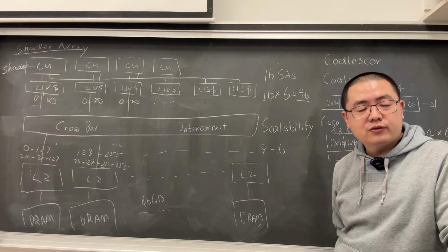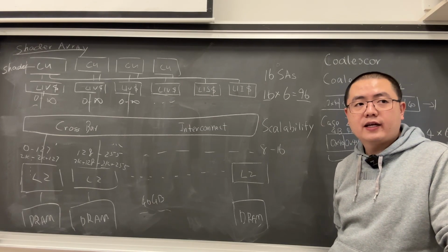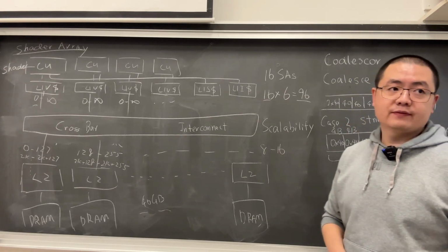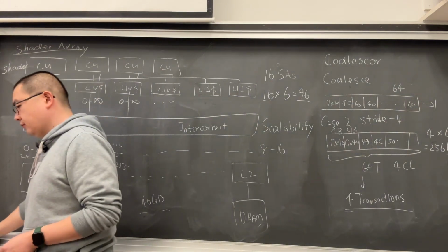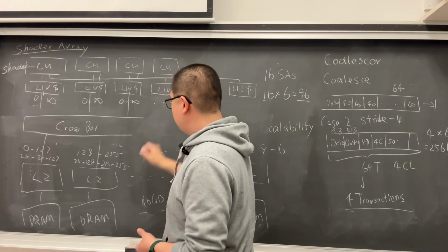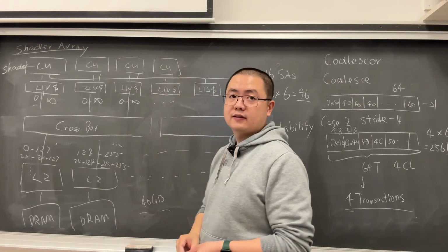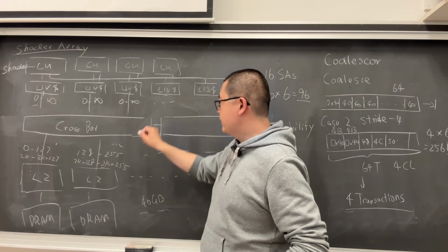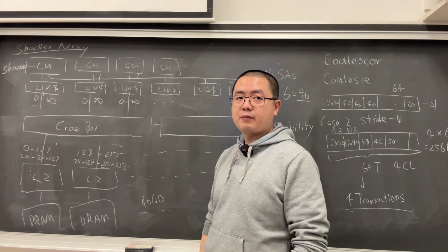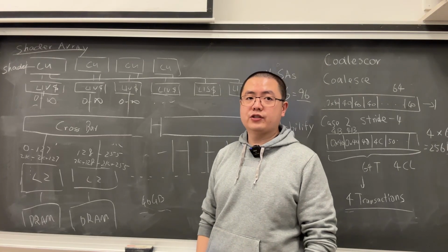Now what can they do? What they actually do in NVIDIA GPUs is partition. So we don't provide one big crossbar. We generate 2 crossbars, and we generate a connection between these 2 crossbars to reduce the number of wires. We connect them together. And this connects to their own L2 caches.